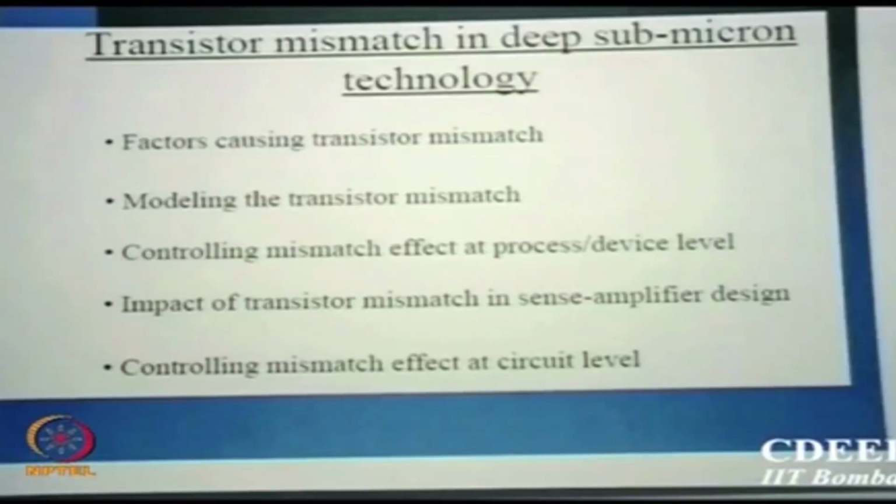The problem which we see in real life is essentially called the mismatch problem. We have already seen in our analysis what can occur if beta is beta plus or minus delta beta. We have seen what kind of actual problems all such variations can create for you. So now how to alleviate some of them? Not that everything can be minimized or removed, but minimization can be tried. One technique is to get into a layout problem which probably can save some of your mismatch problems. So first, look into mismatch.